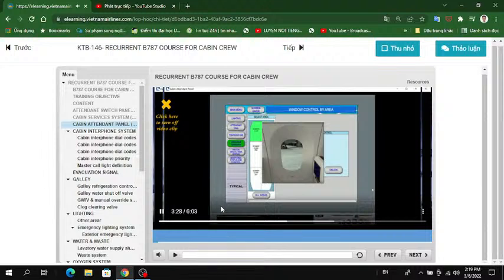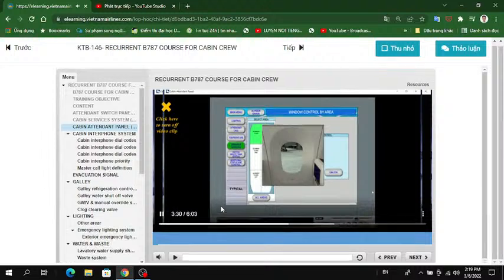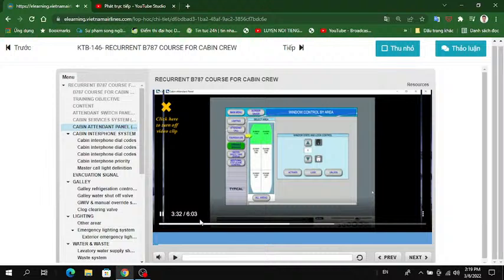Window control is then returned to the passenger. Dimmable windows in the cabin area or all areas may be locked by selecting the Lock soft key. If a passenger selects another level of dimming, the blue light will not illuminate or flash, and the window will not change. Selecting the Unlock soft key unlocks previously locked windows.